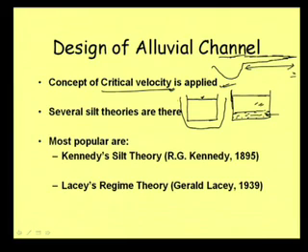Now, if the canal size increases, then the flow depth which was earlier expected to be at this level will come down to this level, and once the flow depth comes down, the distance to which it can travel will also reduce, because the bed resistance, size and everything changes, and then its head reduces. Total head, as we know, is z plus depth of flow plus v square by 2g. Here if scouring is occurring, the z value is coming down. Earlier, suppose the z value was up to this much, the piezometric head was up to this level, z plus p by w or z plus y, but now it will be only this much.